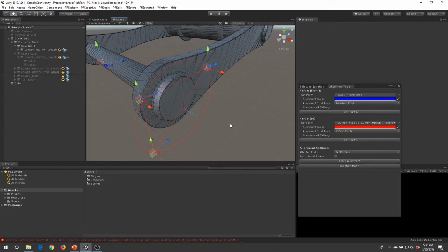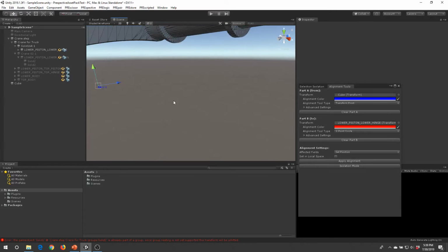To do that, we'll be using the default vector snapping tool that's present in Unity, and a shortcut for that is Shift V. What you'll see is that there's going to be a cube around any selection point. Now if I move it, it's going to snap right onto the vertices. That's what we're going to do. We're just going to move our 3 points onto the circle.